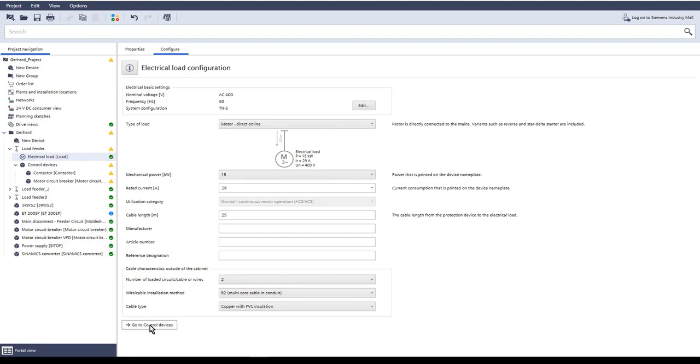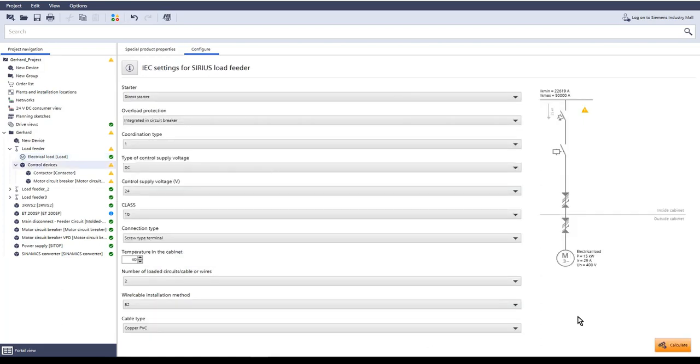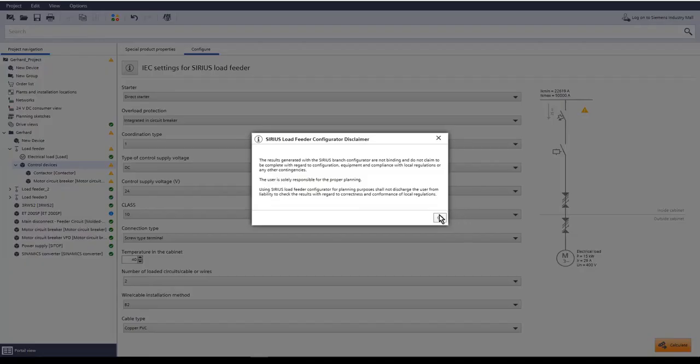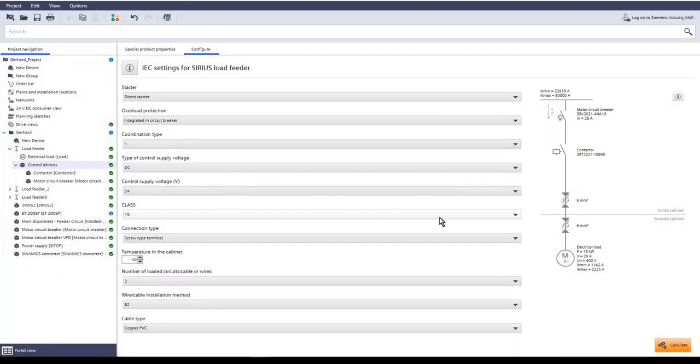Yeah, sure. Is it easy for you to send me the updated sketch, or do you want to tell me the changes right now? I can tell you those numbers right away. Okay, just go ahead. So for the first load feeder on the left-hand side, we have a motor load of 5.5 kilowatts. Is this still the same? No, that's going to be changed from 5.5 kilowatt to 15 kilowatt. Then let's make the change right now. You come here to mechanical power. You select the 15 kilowatt.